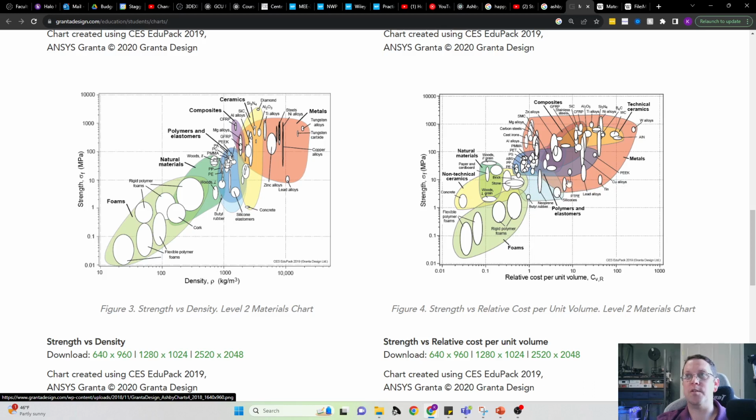They're more expensive. But a lot of the polymers we use, polyethylene, polypropylene, polystyrene, PET, which is what a lot of disposable clear plastic bottles are made of, are pretty tough stuff, relatively inexpensive, but tougher than some of the other materials. That's why we use them so commonly, because you can use less of it and get a better result. Aluminums are sometimes actually more expensive than a lot of carbon steels, weirdly enough, especially high grade aluminum.